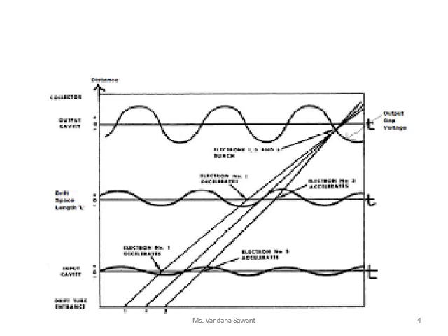In the catcher cavity, the element which is extracting the energy or catching the released energy from the electron is the RF signal. The remaining electrons will be collected by a collector which is present at the other end of the device. Because of the energy caught from the electrons, the amplitude of this RF signal goes on increasing, or we can say that the current of this signal goes on increasing.